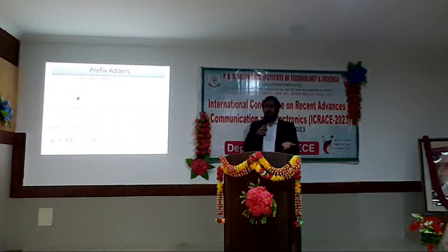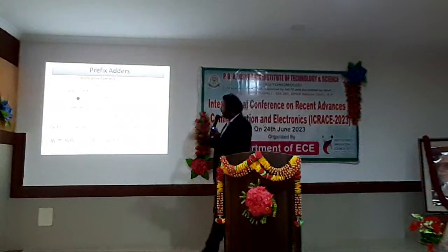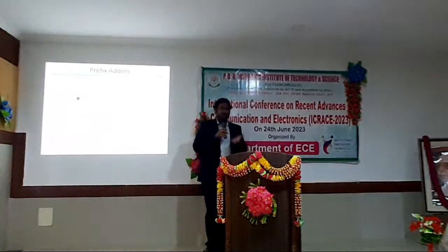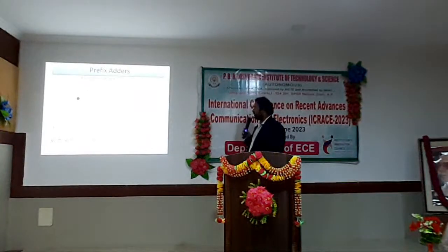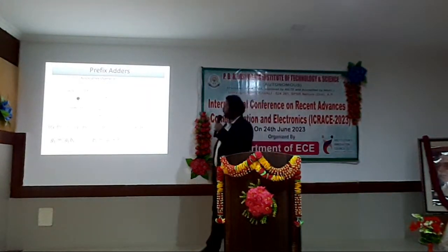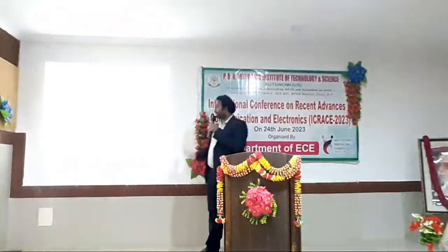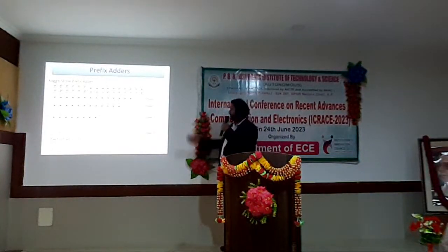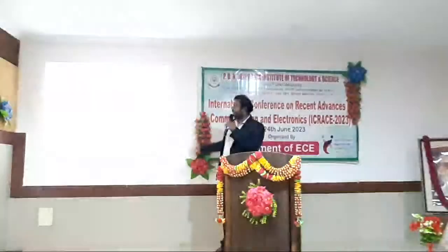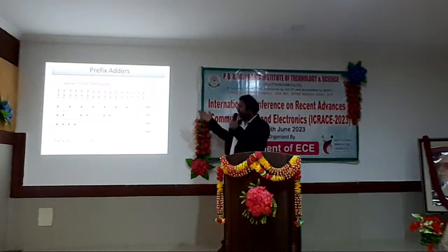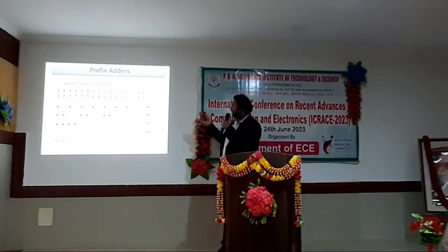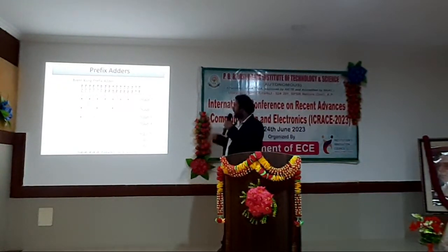How much do you know about binary adders? Correct. All of you know about the ripple carry adder and the carry lookahead adder. But prefix adders are a newer, advanced version of that. They are much better than the carry lookahead adder. You can see the main thing is associative operators. This is the structure of the prefix adders. You can see different variants, and the basic thing in all of them is the prefix operator. Next one.